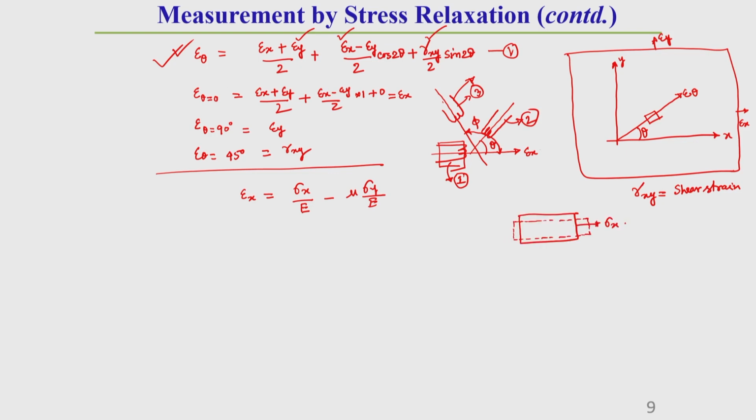So you see, due to the stress along the x axis this body will elongate like this. Due to this elongation you can observe a length increment, but there is also a breadth decrement. Initially the breadth was B0 and the final breadth was BF, the breadth or width you can say, and initially the length was L0 and the final length becomes LF. So generally we can get 2 different types of strains once a body is subjected to a particular type of stress.